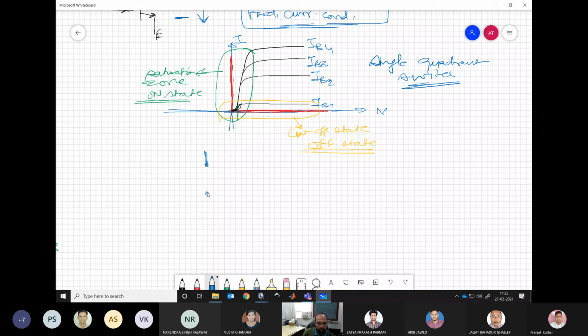It is like an open circuit, with a minimal amount of leakage current and this voltage blocking VCE. So the power loss for all practical purposes, VCE into I leakage, can be regarded as 0.